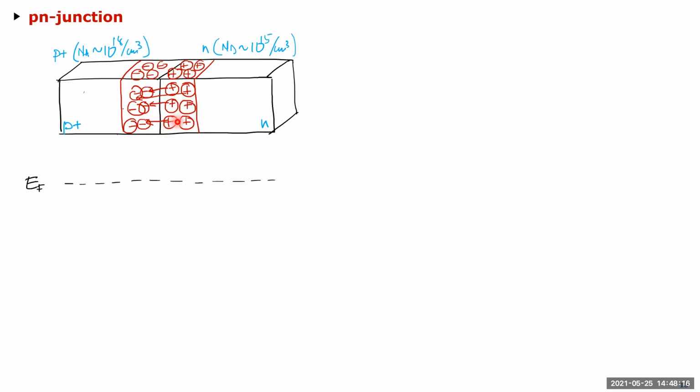So if I draw the band diagram, what thermodynamics tells me is that if I take any material that is joined together, at steady state the Fermi level should be constant. It should remain steady. You cannot have a Fermi level which is going kind of like that in a steady state. And not only steady state, no fields applied either. If I apply some electric field on this side, then the Fermi level will obviously change. But without any fields applied, it's just constant.